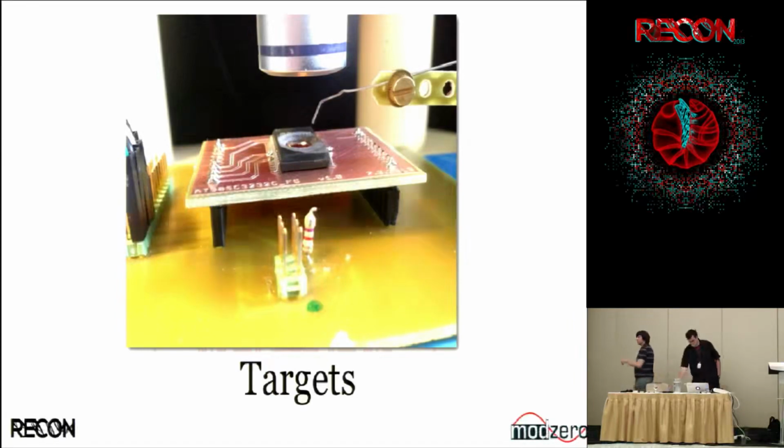So here's one example, which I'll leave to Olivier to explain tomorrow, because he'll do it more justice than I will. You can use this in chip probing, which is one of the things I'm also working on. In chip probing, you want to get signals off of the device, and using the Datenkrake, since it's programmable logic, I can sample the data like a logic analyzer and control the chip at the same time. And if I really wanted to, I could use another port to move around the microscope stage. But we're not going to go in depth with that one.